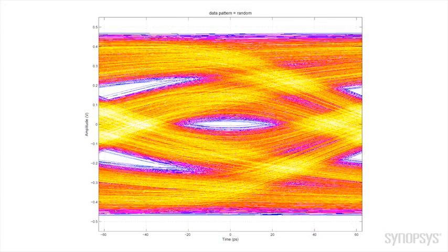An eye diagram is a great tool to assess the quality of a signal very quickly. But some eyes are very fuzzy. Let's take a look at this fuzzy eye that I have here. What causes this fuzziness in the eye diagram? That's a really good question, Rita, and it's an important question in the field of signal integrity. When we see this fuzziness, the cause is a type of distortion known as intersymbol interference. So what is intersymbol interference?